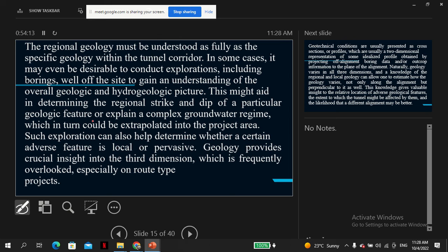But again, you should remember that the direction or the route is determined by the designed alignments that have to follow certain curves or certain rules of certain radius. So if for example the design, ensuring the safety design, the radius or the alignment makes the tunnel pass through some hazard, then of course the design team has to rethink to make sure that the hazardous place is avoided. Of course, certain times it's impossible to.